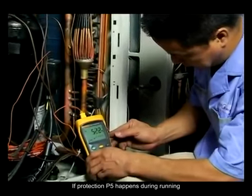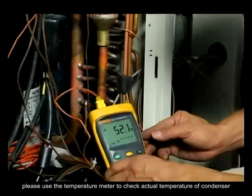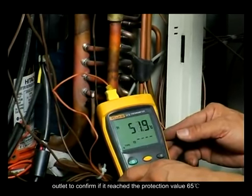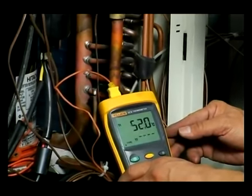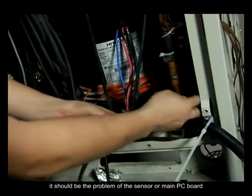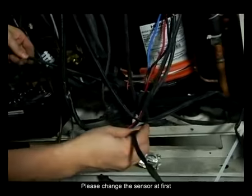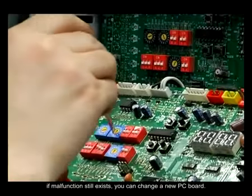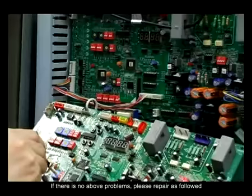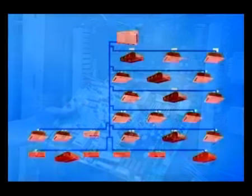If protection P5 happens during running, please use the temperature meter to check actual temperature of condenser outlet to confirm if it reached the protection value 65 degrees Celsius. If the actual temperature is in the normal range, it should be the problem of the sensor or main PC board. Please change the sensor at first. If malfunction still exists, you can change a new PC board. If there is no above problems, please repair as followed.